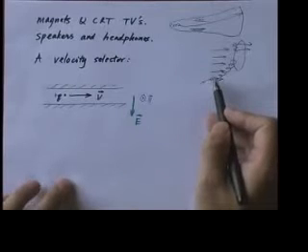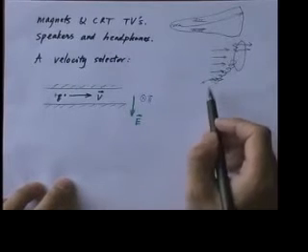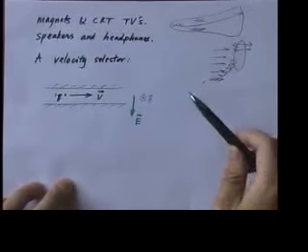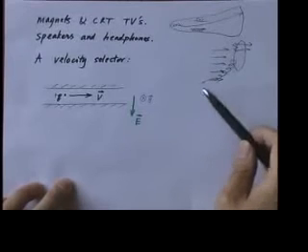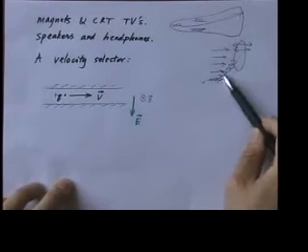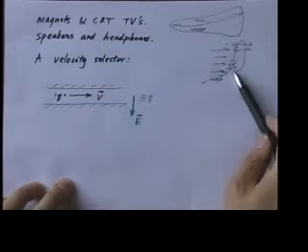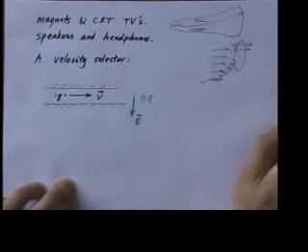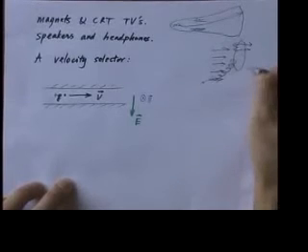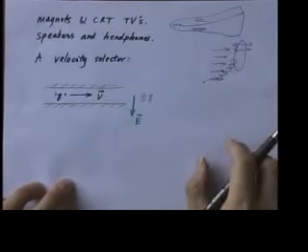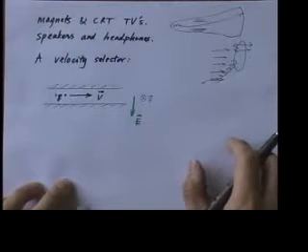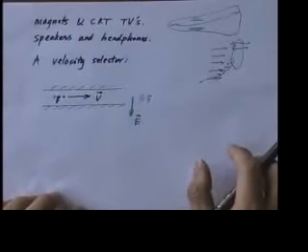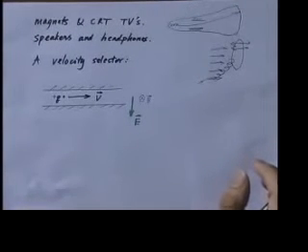So, as you speak into the microphone, it turns your sound signal into an electrical signal, which is amplified to produce the current driving the diaphragm. Then the diaphragm starts to oscillate, causing the air around it to compress and decompress, and that is the sound that we hear. So you see, in a conventional speaker, we do need a strong source of magnetic field.